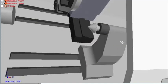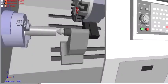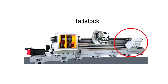The next part is the tailstock. In a CNC lathe, the tailstock is used for supporting the workpiece axially. Whenever we have a lengthy workpiece for machining, we take support of the tailstock center. The tailstock position can be adjusted along the lathe axis.